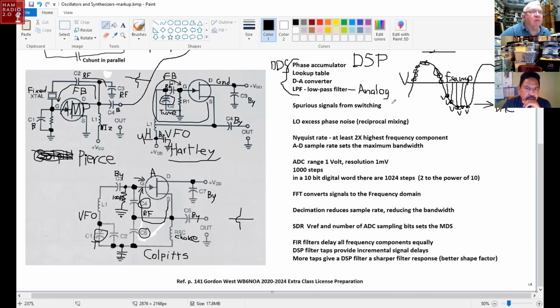Okay, however, by doing this, there's a little bit of noise because you don't exactly represent each value of this sine wave. So you're going to need a low pass filter to filter out this real high frequency noise, because the D to A converter isn't going to interpolate between here. All it knows is the digital word that you sent to it. So this voltage comes out and then this voltage comes out. So for this amount of time, this is the voltage you get out. It's just straight across. Then the voltage jumps to this sample and the voltage is straight across, and it jumps to this sample, and here it's straight across.